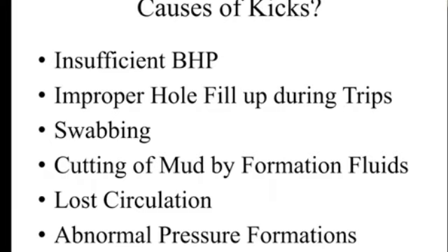If for any reason formation fluid starts entering the wellbore and contaminates the drilling mud and reduces the mud weight. If lost circulation happens, so the level of the drilling mud inside the annulus drops, consequently bottom pressure drops, kick happens. Or if we are drilling and none of these happens, and we start entering abnormally pressured formations.